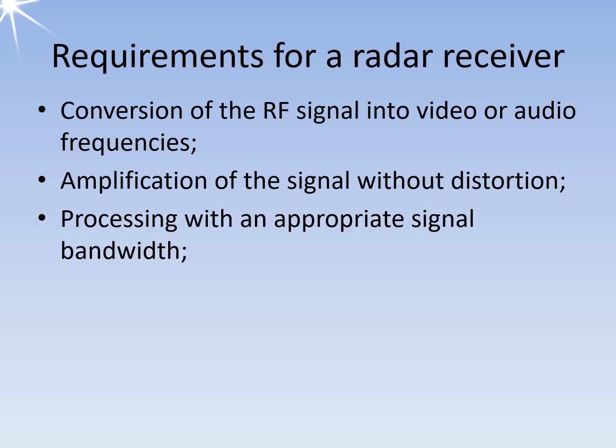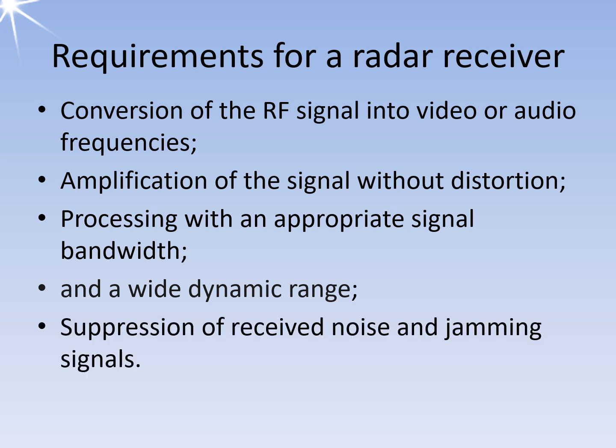Optimization of the probability of detection of targets by selecting an appropriate receiver bandwidth, and enabling a wide dynamic range to adjust for small echo signals amid large interference from fixed targets. In the radar receiver, noise and jamming signals are to be suppressed and unwanted echo signals from fixed targets are to be attenuated to optimize the target location.